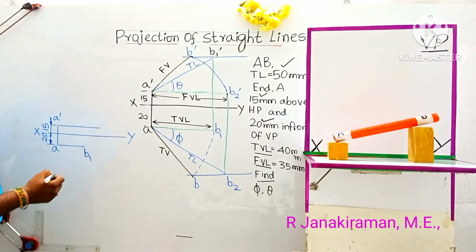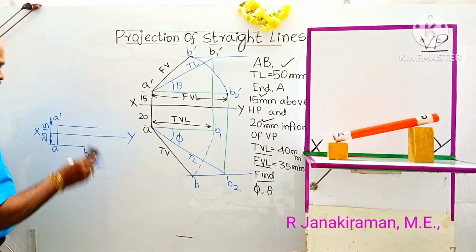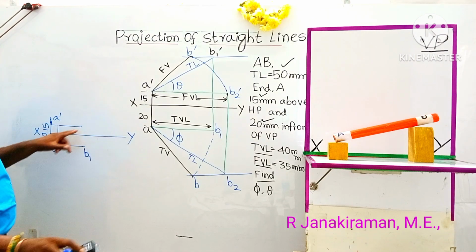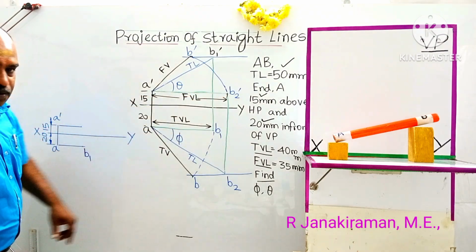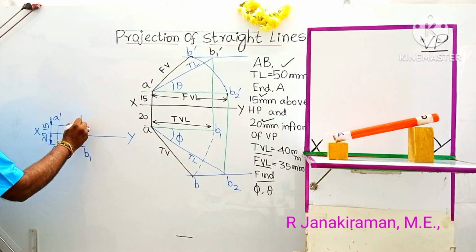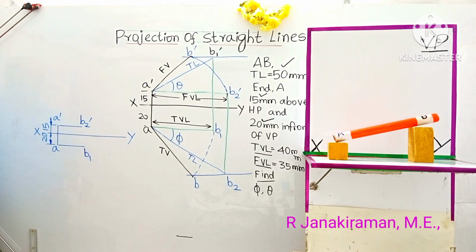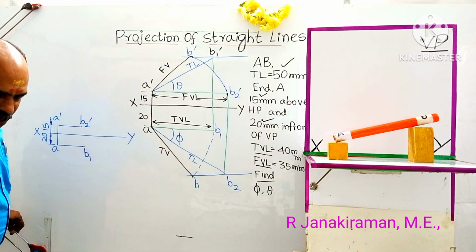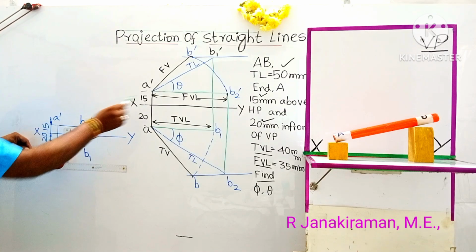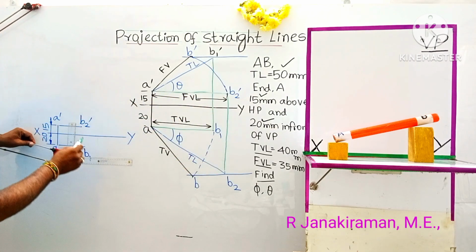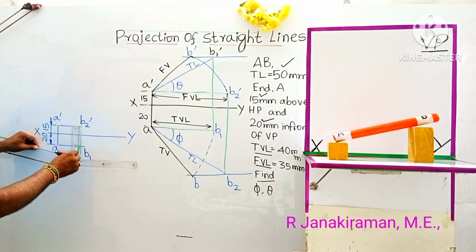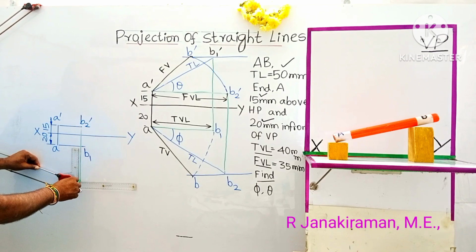Okay. So this is 35 and that is 40. Remaining length you can erase it. This point is called B2. B2 dash. Next, using 2H pencil, draw various projectors. From B2, this is a downward projector. Draw a downward projector using 2H pencil.